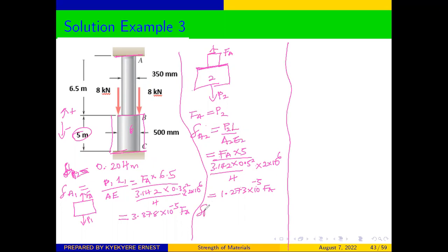should be equal to 0, because this rigid support will not allow the bar to elongate. And therefore, we stated that looking at the direction of our free body diagram, this deformation as a result of the external forces is going to be negative. The value for that was 0.204.